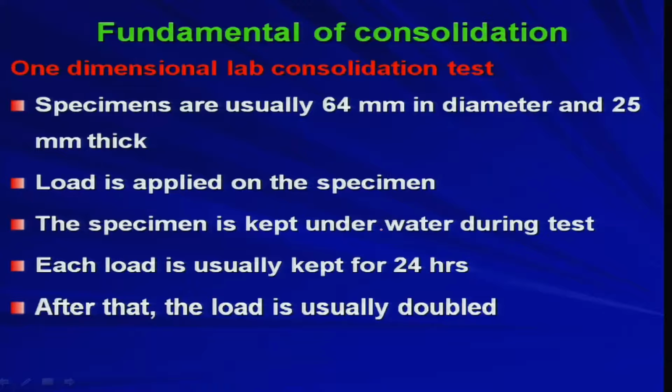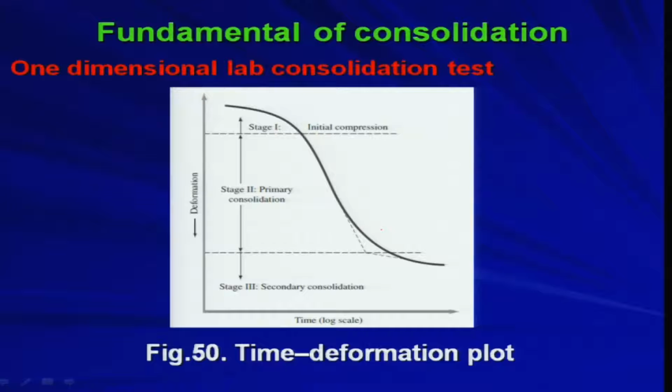So, after that the load is usually doubled. So, that means whatever load you applied initially, now you are doubling the load, and then you observe the same thing, that how much will be the deformation. You wait for another 24 hours and then you see. So, now you will be getting a plot like this, this is the time deformation plot. Now, you see the deformation is plotted on the y axis and time is plotted on the x axis, that is a semi log plot. Okay.